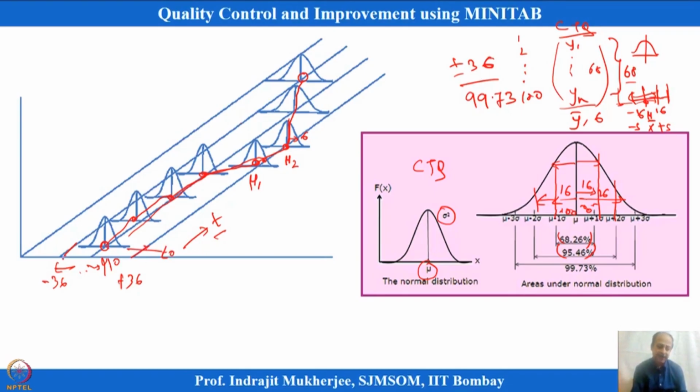In this case, what is expected is that the mean or any average value at a given time point, let us say I have taken 5 observations and I calculate the average of that, should be within plus or minus 3 standard deviation. That is the assumption we are making from the normal distribution over here. Also, we take the average value, we do not believe in one observation. Sometimes at a given time point, we take multiple observations.